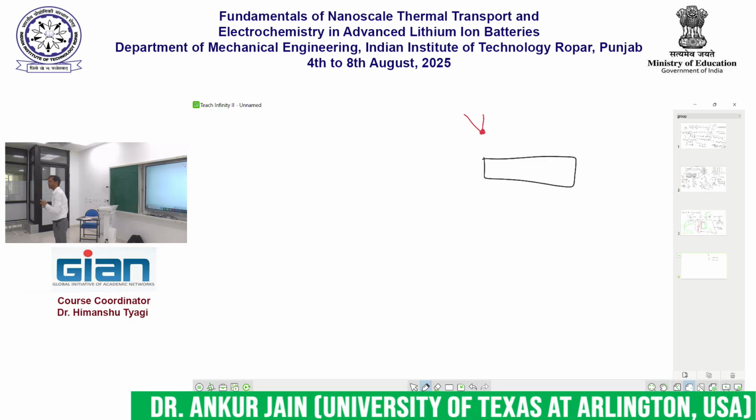The thinner your bead, the better your measurements are going to be, because the thermal mass of this bead plays an important role. You see, this thermocouple does not measure temperature instantaneously, right? The thermocouple that is in touch with my cell, once the cell gets hot, the bead of the thermocouple will get hot, and therefore a potential difference will be formed. This process does not occur instantaneously, and therefore the thinner the bead, the better it is.